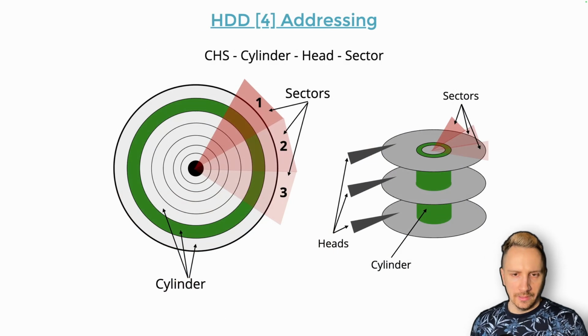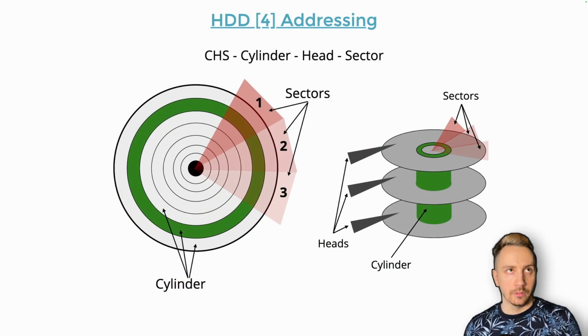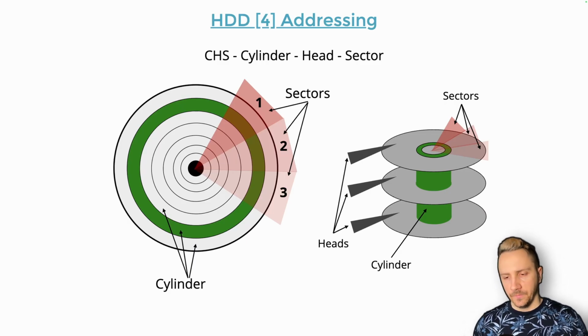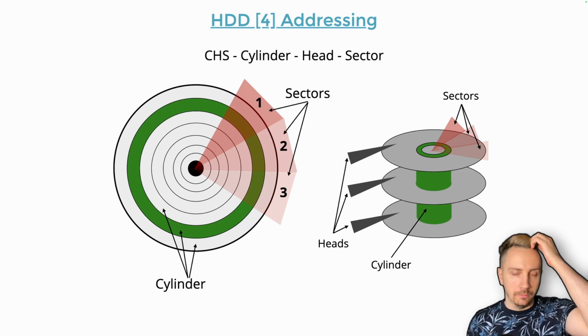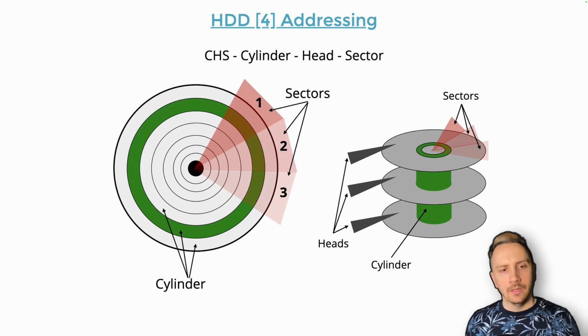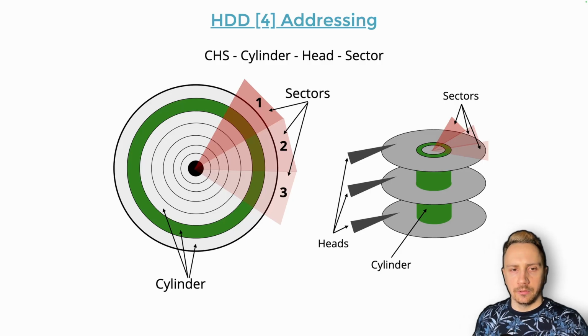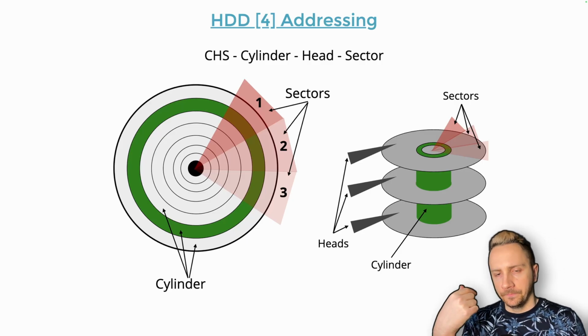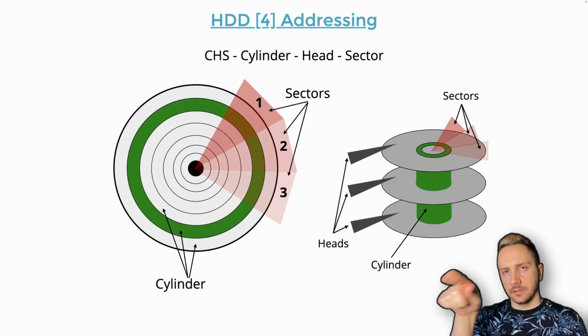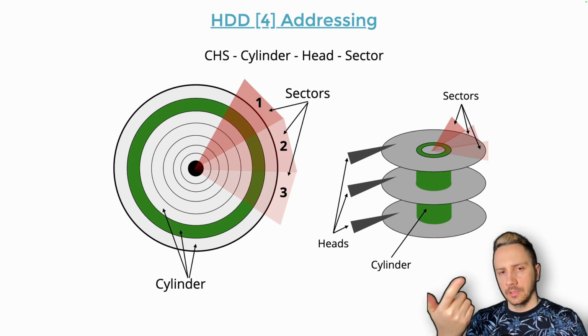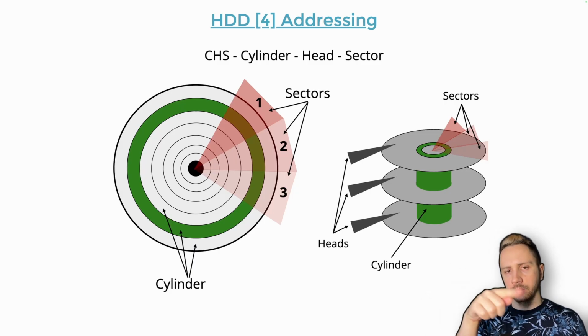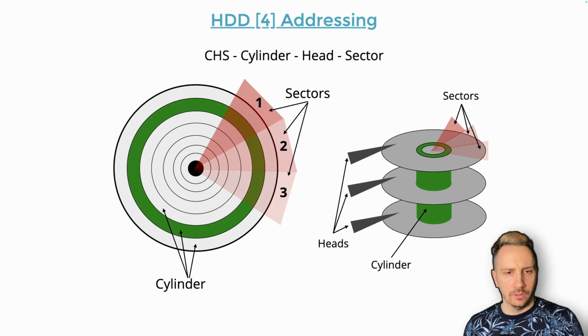The next question then is that since we figured out how to store individual domains and to read them, how are individual bytes in these devices addressed? Because it's not just an array of bytes, right? It's multiple disks, multiple floors, and on them the data is stored in circles, because when you position the reading head on top of the disk and the disk is rotating, if the head is not moving, then you have a circle which will go under the reading head. We need to find a way to address this 3D structure as actually an array of bytes.